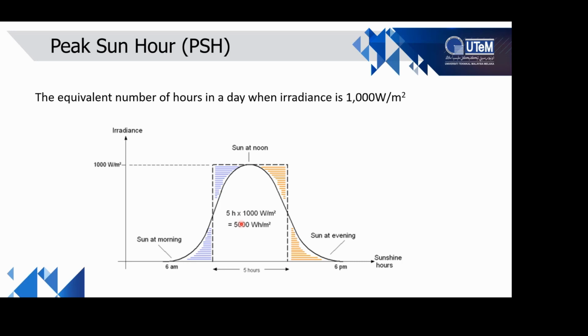But anyway, if you ask me the second question, what is the maximum DC-AC ratio based on your opinion? I would say there's no definitive answer. There's no definitive answer. I would say I will also follow the range between 1.1 to 1.5, depending on the design, depending on the budget, and depending on the expected energy we want to generate.